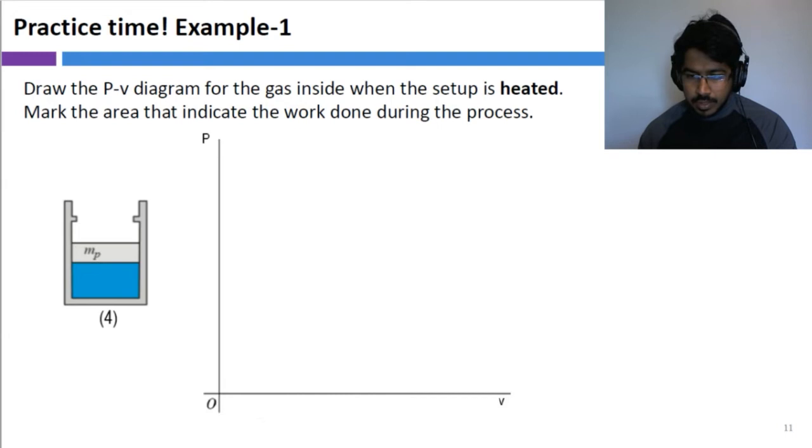Perfect. So isobaric and isochoric, and when this says we increase until the piston touches the top, and P keeps the same, and then increase where the piston touches the top. Perfect. Both of you are right. That is very good, right? So what we have here is similar to the previous example. The pressure inside the gas is just enough to hold the piston, right? When we heat it up, the gas tries to expand, but there's no resistance. Therefore, the pressure will not be increasing, but the volume will be increasing until it hits the stops.